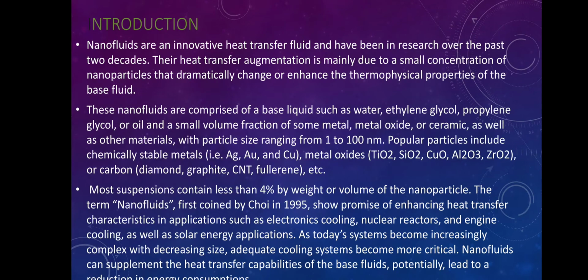Introduction. Nanofluids are an innovative heat transfer fluid and have been in research over the past 2 decades. Their heat transfer augmentation is mainly due to a small concentration of nanoparticles that dramatically change or enhance the thermophysical properties of the base fluid. These nanofluids comprise a base liquid such as water, ethylene glycol, propylene glycol or oil, and a small volume fraction of some metal oxide or ceramic, as well as other materials, with particle size ranging from 1 to 100 nanometers.